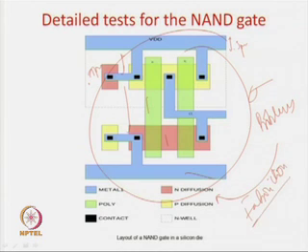So, what is the difference between verification and test? In verification, what do you verify? You verify that I wanted to design an adder, so whether the code I have written really implements the adder. That is what I verify: whether it is functionally what I intended to design. If there is any failure in the verification phase, then you can be sure that it happened because of the designer's mistake.